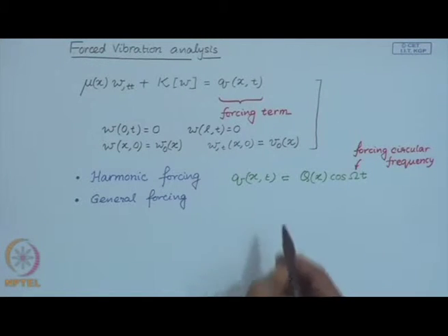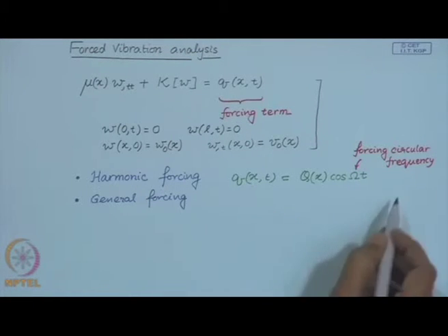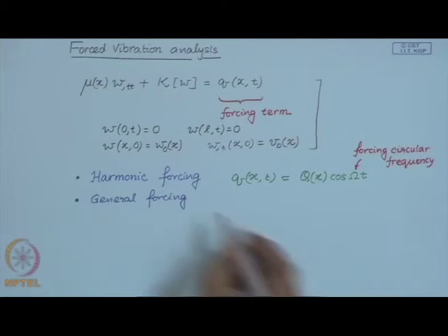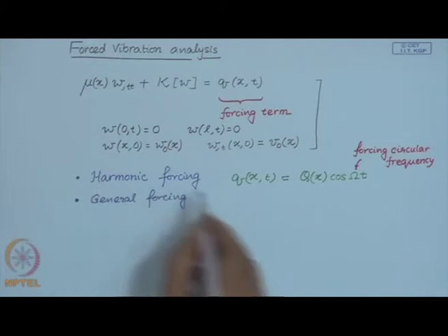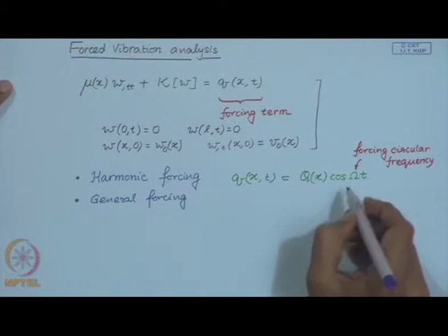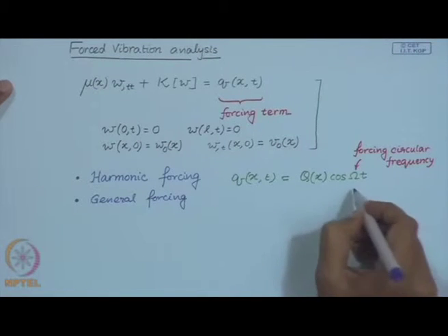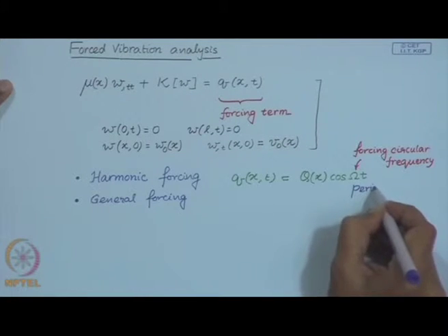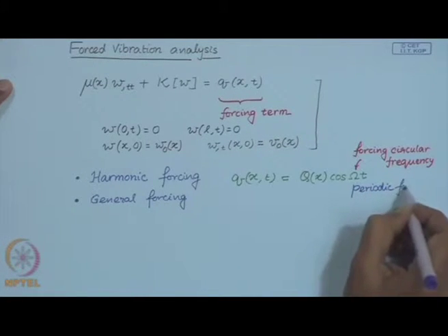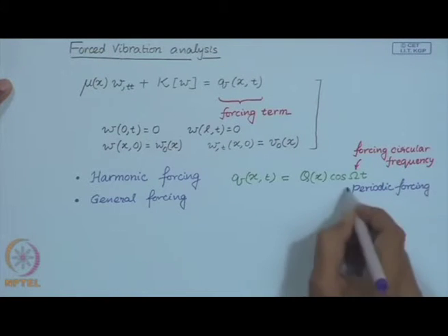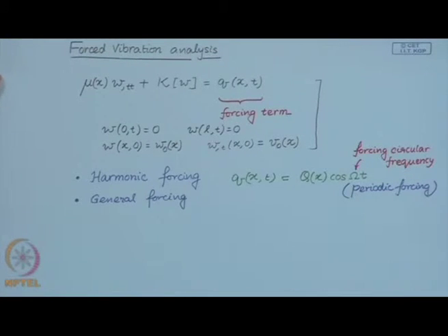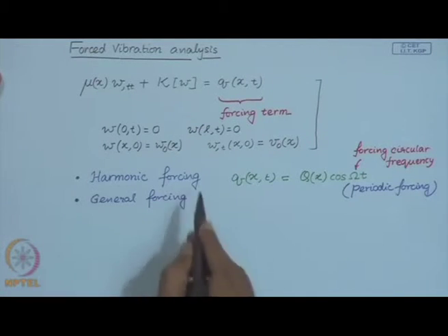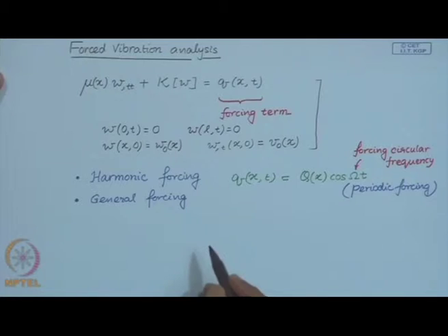and this is the temporal variation of the force. And any periodic forcing, as you know, can be represented as a series of harmonic forcing. So, if you know the solution for the harmonic forcing, then you can also find out the response to any periodic forcing. So, we can also deal with periodic forcing if we know how to find out the response to harmonic forcing.